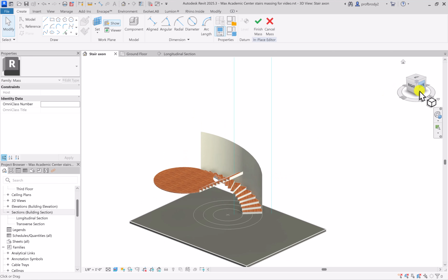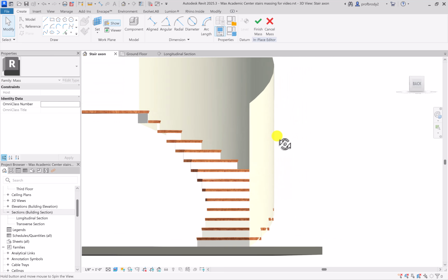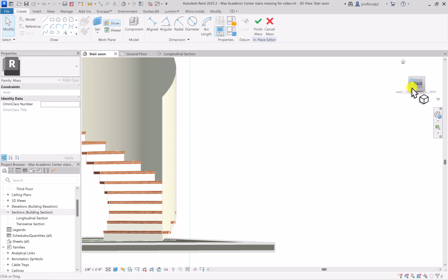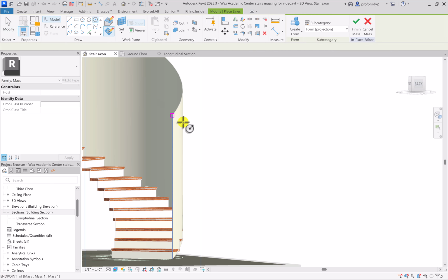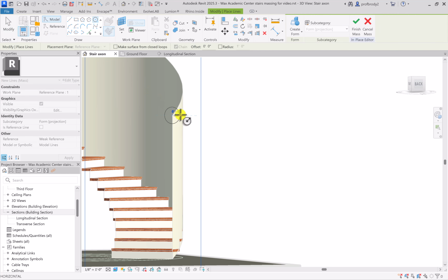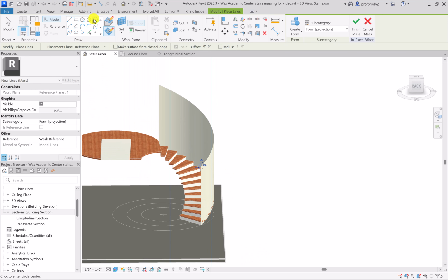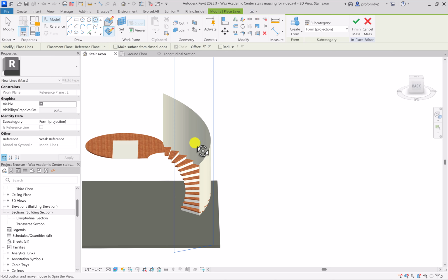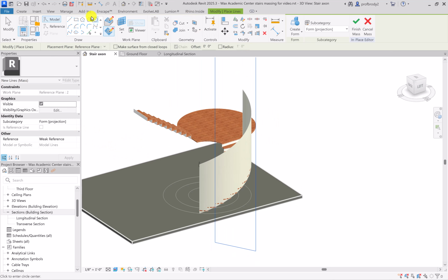You see how it highlights reference plane there vertically. And it's a little tricky. I could put it in this front view, but you can see it's not totally flat there, but we can get pretty close. And we could try drawing a circle for, say, the top of this wall. I'm going to make it big at first because it's really hard to draw. And now, let's say I want to create another circle. I just click the circle button. But up here, I can choose which reference plane it goes on. See how it's swapped? Now I'm halfway up. And in theory, anyway, I could draw this circle at the top of this wall.